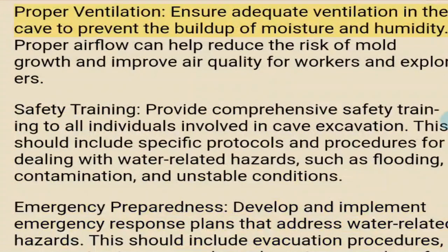environment. Proper ventilation. Ensure adequate ventilation in the cave to prevent the buildup of moisture and humidity. Proper airflow can help reduce the risk of mold growth and improve air quality for workers and explorers. Safety training. Provide comprehensive safety training to all individuals involved in cave excavation. This should include specific protocols and procedures for dealing with water-related hazards, such as flooding, contamination, and unstable conditions.